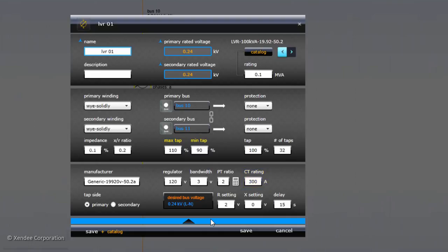This value is a rating for converting the line amps to control amps. And as mentioned earlier, the control needs to know the values of resistive and reactive voltage drop for the line when the line is carrying the primary rated current of the CT. These R and X values are calibrated on the control in volts and not ohms. Beckwith Electric has a nice document on how to estimate these values, and most controls have a range for R and X between -24 and +24 volts.